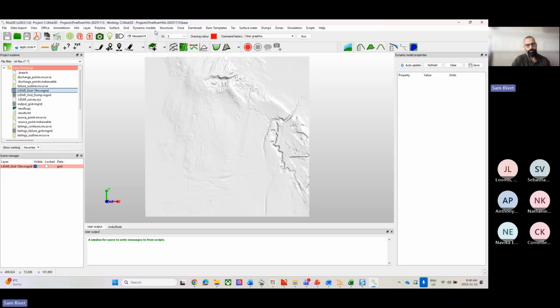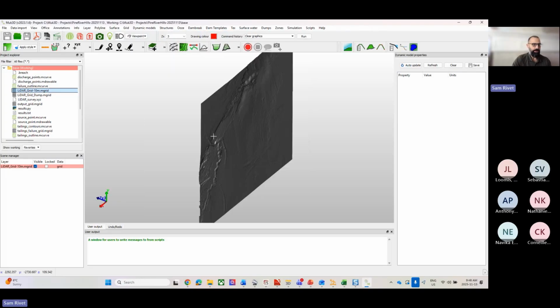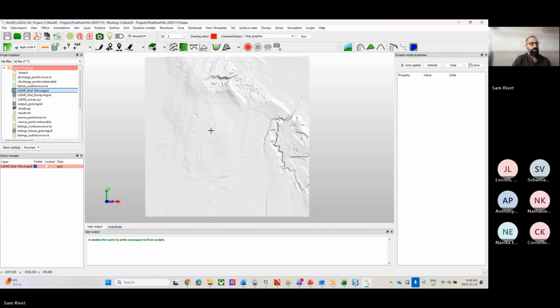All right, so for this next function, for each tailing dam, we need 3 grids. We need this original ground, which we have. We need a grid with just a dam built, no tailings, or what we want to consider being freshly placed tailings. And then we need a grid with the dam plus tailings. So let's start by creating just a surface with a dam merged in.